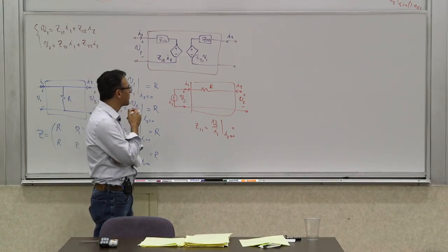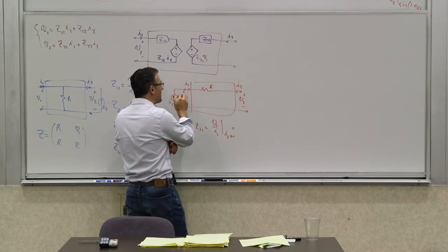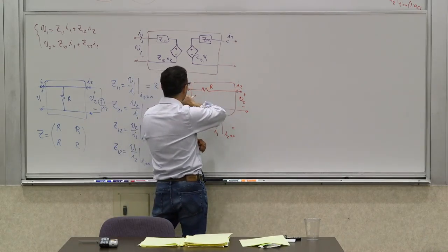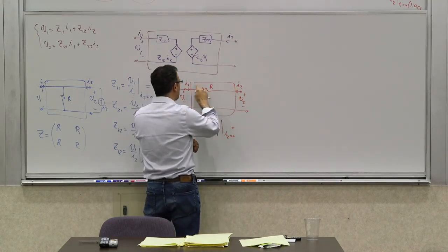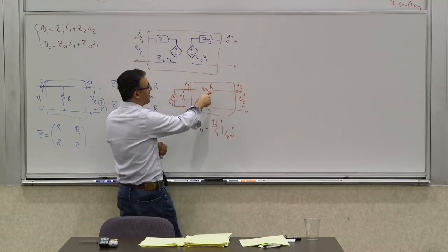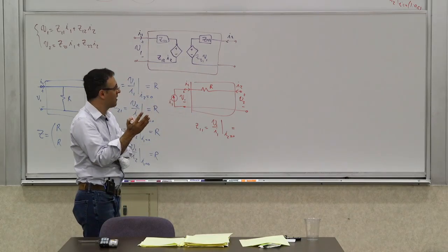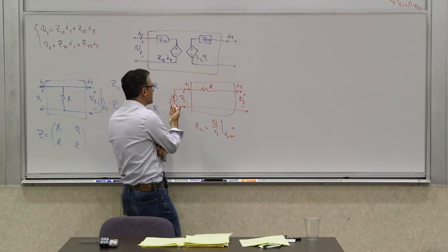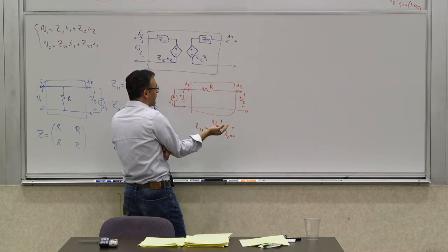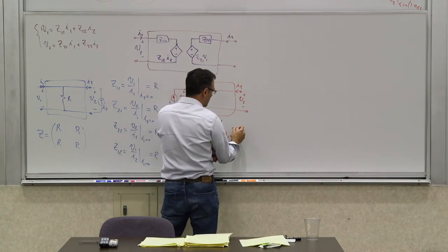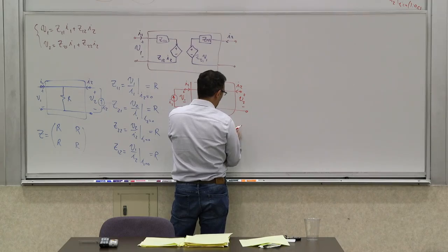Well, we clearly have a problem, right? Because if you think about this, you're trying to inject a current into this thing while the other end is open. Since I2 and I1 are essentially the same with a minus sign, you cannot force an I1 into this thing. It would basically produce an infinite voltage, which would not be appropriate. So this becomes undefined, or it goes to infinity and things of that sort.